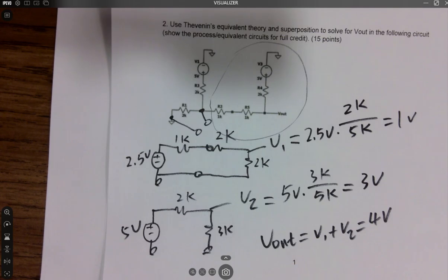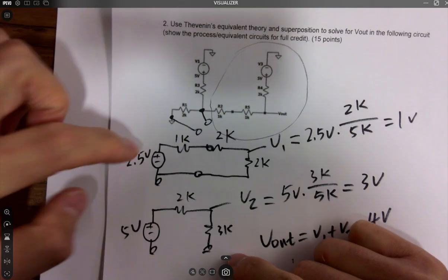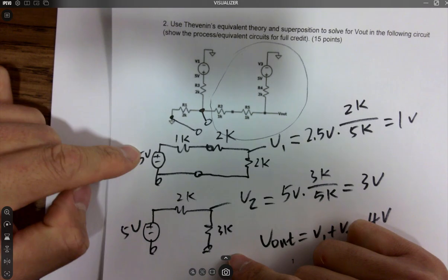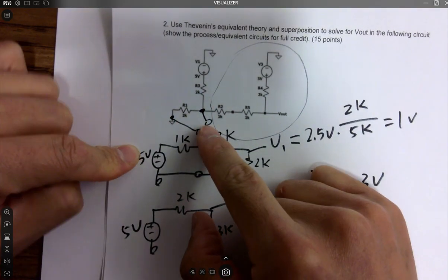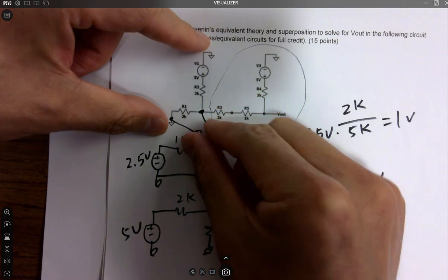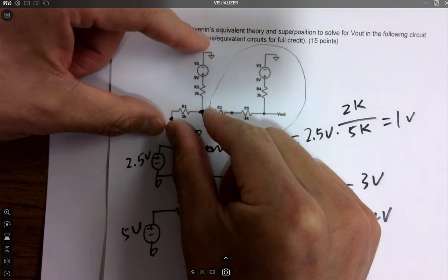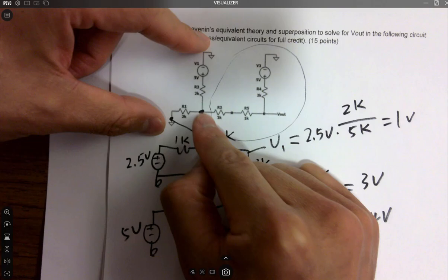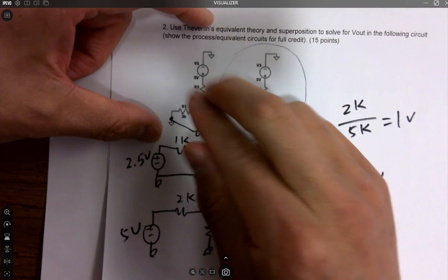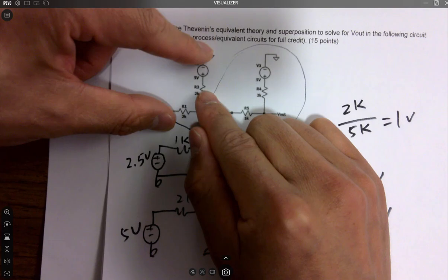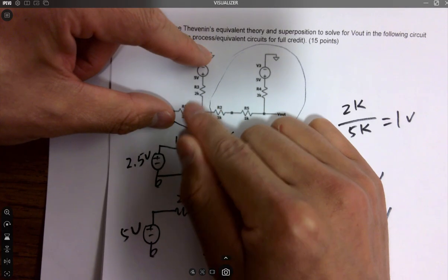So you just combine the first 2 resistors in parallel, right, to get that 2.5 volts? And then this guy or this guy? The first one. This one? 2.5 volts. Yeah. You mean this part? Yeah. Yeah, it's a Thevenin's equivalent, right? So when you just look at this part, this is the output node, right? Yeah. And you're looking backwards from here, right? It's 2 branches and go to ground. Yeah. So it's 2 parallel, 2K in parallel, it's gonna be 1K, right?